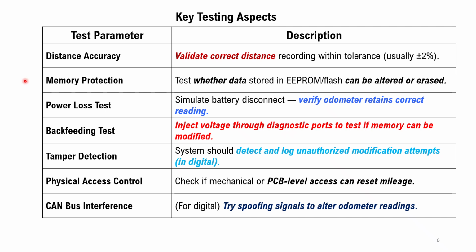Power loss test. Simulate battery disconnect. Verify speedometer retains correct reading. Backfeeding test means inject voltage through diagnostic port to test if the memory can be modified.